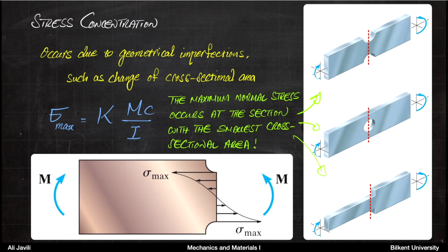So what you get is something like this. The stress distribution that you would see here is now the actual stress. It's not linear because you have the stress concentration factor. If it was the linear function, it would have been something like this. But importantly, you are looking at the stress distribution on the smaller part. We are not looking at this one because we know whatever this distribution is, it is smaller than what you have here. So the critical area would be this one.